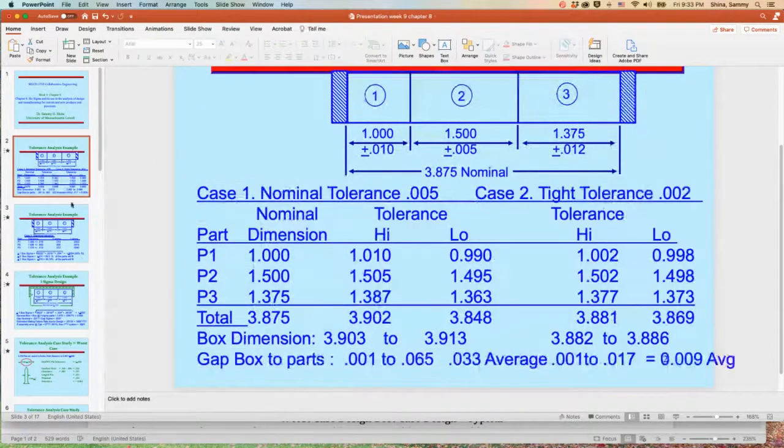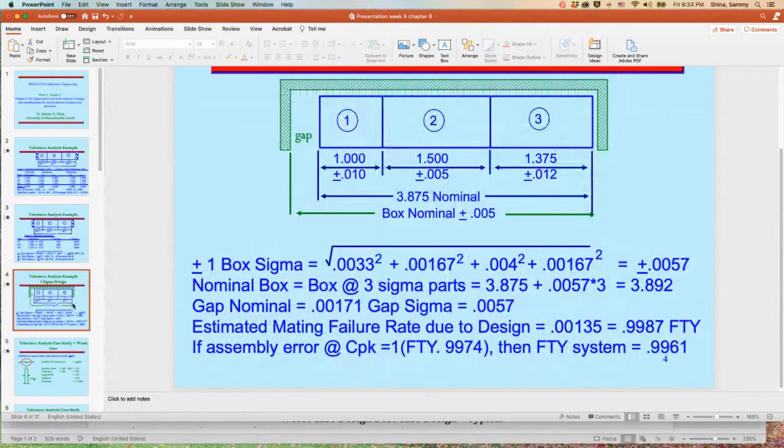We go back to the previous one, and that's so much better than the worst case design, which is much heavier in specifications, because we don't have to reduce the tolerance to 0.02. We can essentially reduce the tolerance to 0.05, no problem. Okay, so that's an example.